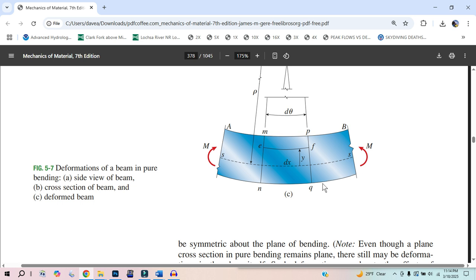Now, it seems like strain, you want like a number 2 in there, like a 200%. But no, you're 100% increasing the length. So strain is the percent increase in length. It's actually pretty simple: it's change in length divided by original length.